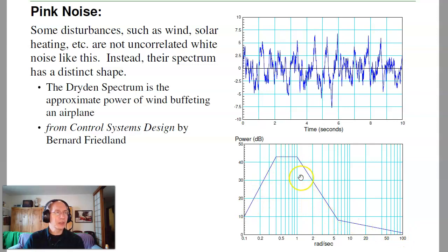The spectral content looks kind of like this. If I take white noise and run it through a filter with this gain versus frequency, that's what I get. Again, if I go over a span of say 1 or 2 seconds, there's almost no correlation. But for a brief instant, there's a high correlation. If the wind was blowing strong right now, it's probably going to be blowing very strong 10 milliseconds, 100 milliseconds from now.